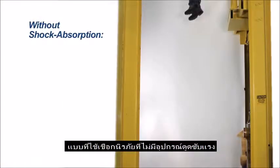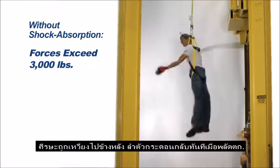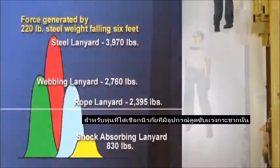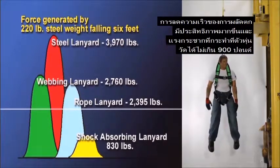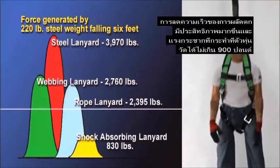Without shock absorption, forces exceed 3,000 pounds, causing the head to snap back and the body to bounce at the instant of arrest. With a shock-absorbing lanyard, deceleration is much smoother and more controlled, and fall forces are contained to 900 pounds.